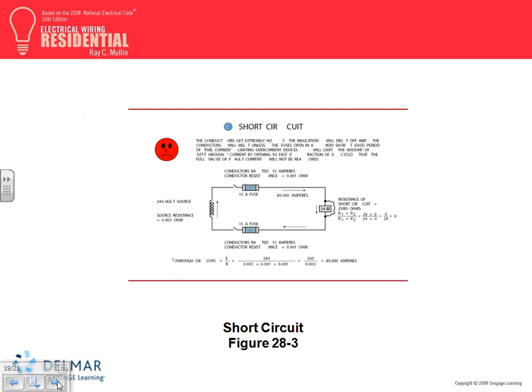Okay, a short circuit. Look what happened with a short circuit. A short circuit, guys, this is extremely important. You bypassed the load. You basically grab the 2 hots and tie them together. Now, Spencer, the impedance, what happened to the 24 ohm? The 24 ohm is gone now.